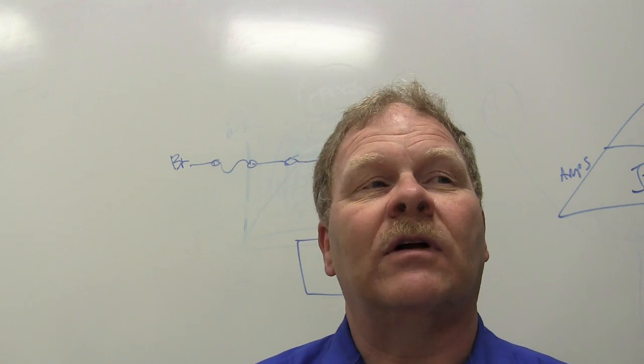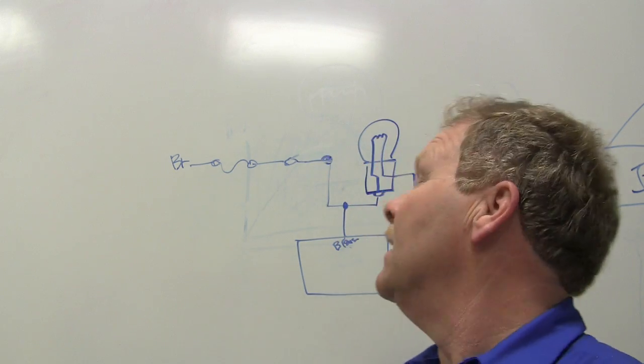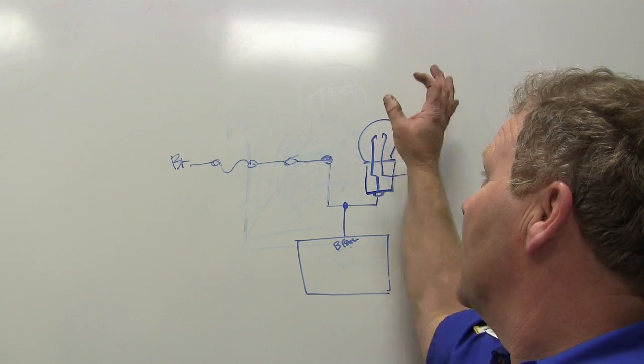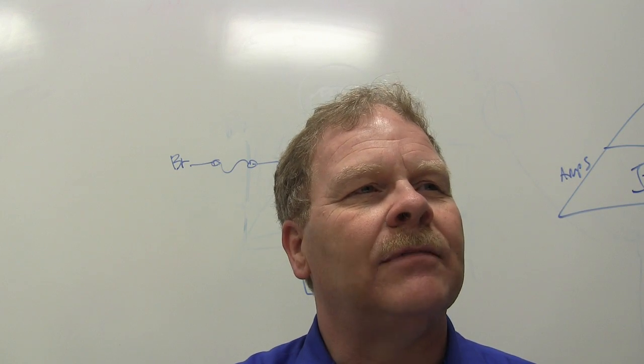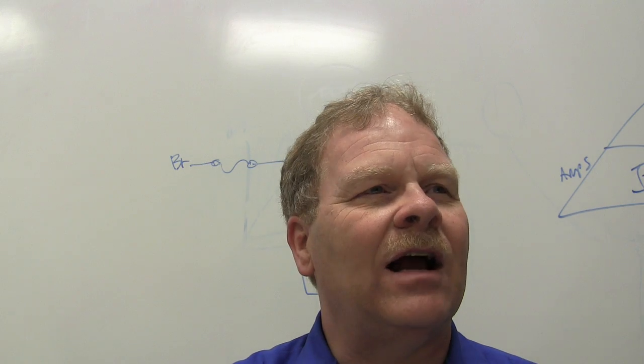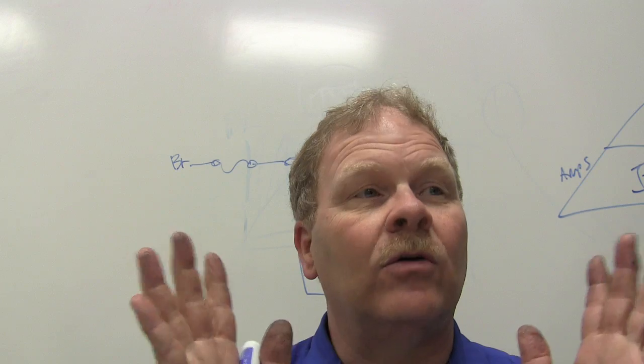The way we know that's what it's thinking about is if I had one I wanted to get you guys to troubleshoot, I could come along and put a couple of blown bulbs in there and the cruise wouldn't work, because it ain't seeing the ground. Now, one blown bulb won't do it, two has to be blown. It has to have no ground at all.